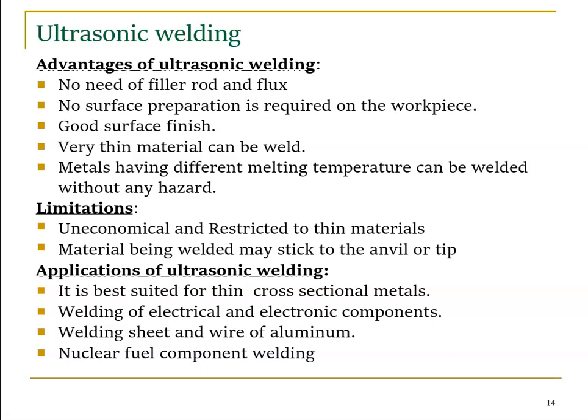Applications of ultrasonic welding are: it is best suited for thin cross-sectional metals, welding of electrical and electronic components, welding sheet and wire of aluminium, nuclear fuel component welding. These are the applications of ultrasonic welding.